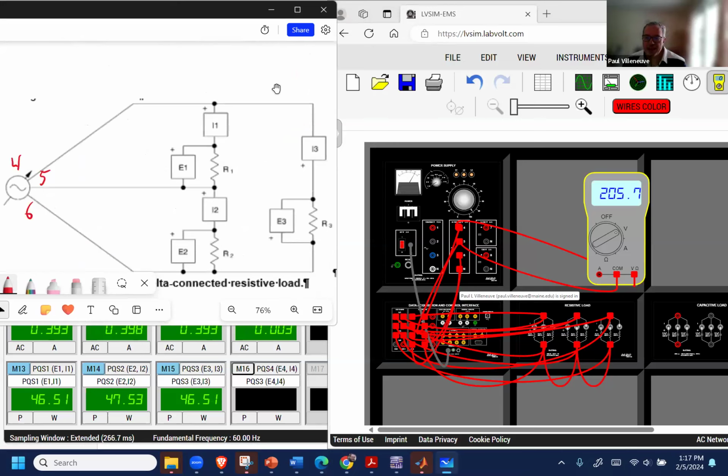And then the other thing is the currents. Get this out of the way, you can't see, but the phase currents and the line currents should be the same. And we'll see when we look at the next part, we're going to go ahead and get the results. So your phase current should be the line current, which is the same values that you calculated. The average current there is just adding the 3 up and then dividing by 3. And then you should get the same results.